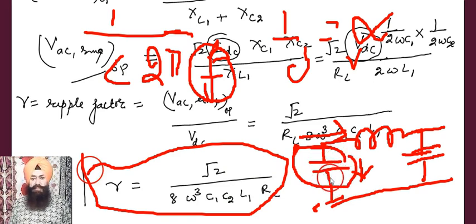But low frequencies find some difficulty, because if F is greater, reactance will be less. So higher harmonics will be grounded, but the lower frequencies cannot pass through the capacitor, so they go to the inductor.